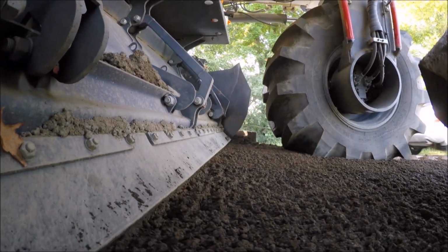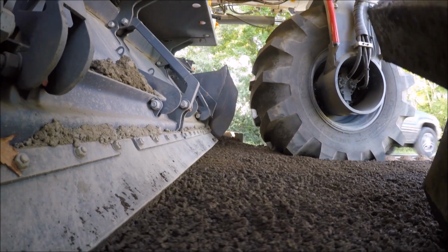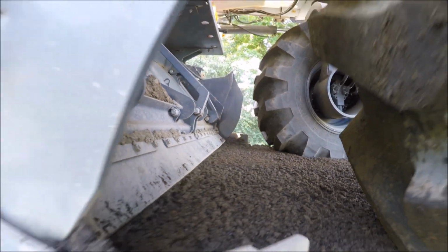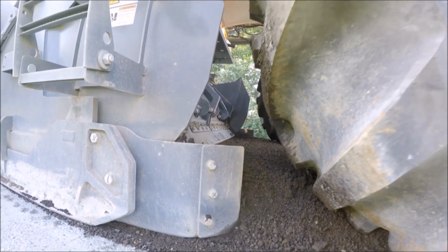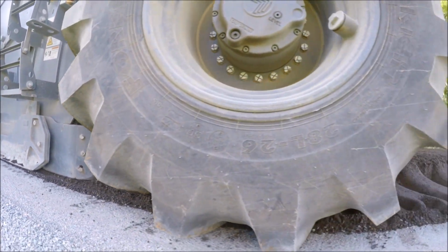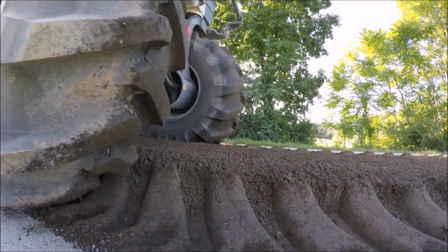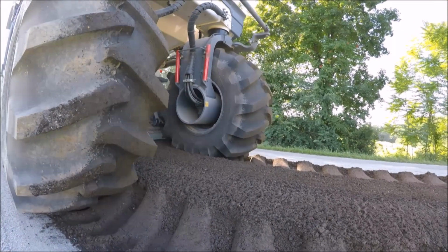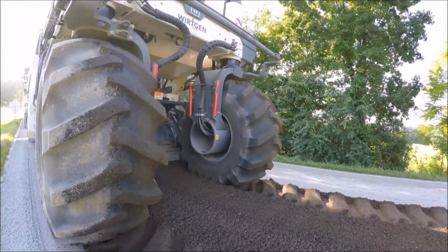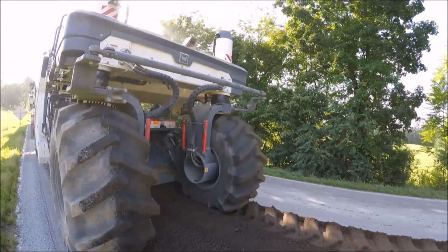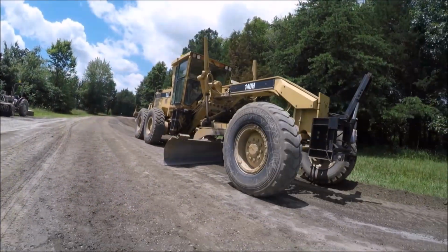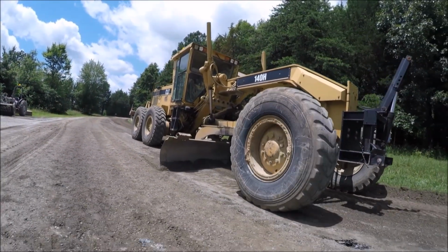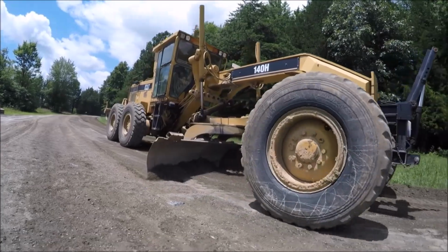This machine is not a crushing operation. It is a sizing operation, so the size of your stone is typically going to be your particulate size of material. He's cutting right now about 10 inches deep. He's also hydrating it as he goes through. In this particular case, they're using Portland cement, so the hydration of that cement will go smoothly. Here, he's doing some rough grading.